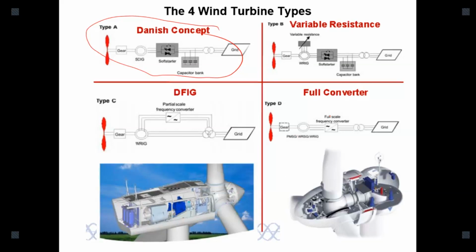Now, these two are the most commonly used systems at present. The propulsion system, the DFIG one, we are going to talk about in detail. The generator has a stator and rotor, with two winding systems, a rotor winding and stator windings. The generator rotational speed depends on the stator and rotor frequency. In this case, we can change the stator frequency by using a frequency converter. Now this rotational speed can be varied to comply with the variation of wind speed. That's the DFIG one.